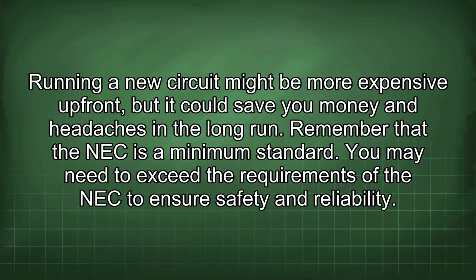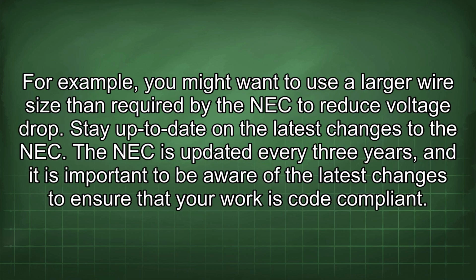You may need to exceed the requirements of the NEC to ensure safety and reliability. For example, you might want to use a larger wire size than required by the NEC to reduce voltage drop. Stay up to date on the latest changes to the NEC. The NEC is updated every 3 years, and it is important to be aware of the latest changes to ensure that your work is code compliant.